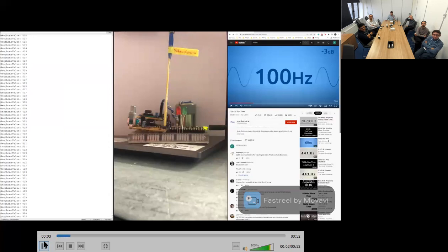As you can see on the communication port, the device continuously reads the geophone value, and as soon as I give a vibration by putting my hand on the desk, we get the message. By the way, it's just for demonstration. It slows down the Arduino sampling speed, so we're not going to use it on site, but just to demonstrate how the device is working, I wrote that code to show off. So it shows the vibration detected and it gives the detection time.